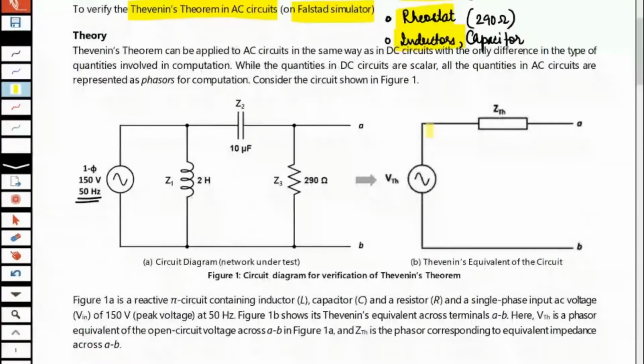Question is that you need to find the Thevenin equivalent of this circuit which is given, right? So finding Thevenin voltage should not be a problem at all, because you just need to connect the circuit like this, and you know that VTH is nothing but V open circuit. If you're finding across these two terminals, all you need is the open circuit voltage. Take a voltmeter or multimeter, put it across these two terminals, and that should give you the value.